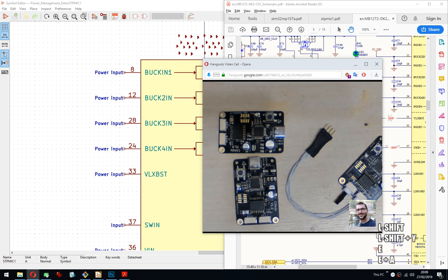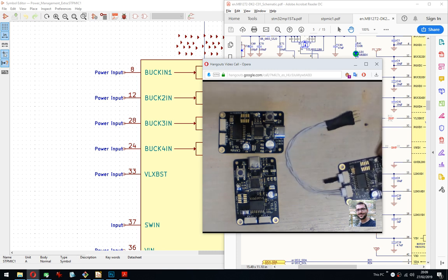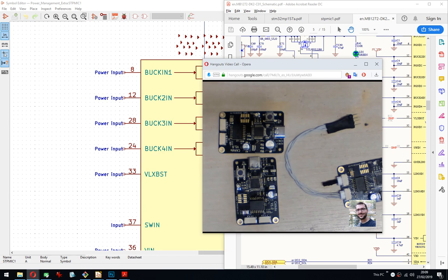Yeah, there's a hot glue gun and the oscilloscope and lots of tape and components and FPGAs and whatever. But yeah, I plan on doing some rudimentary TX testing and looking at the frames, if I'm even capable of sending anything, because I've figured out that the issue I was having, that I can't pull up the CAN device on Linux, was because the CAN transceiver wasn't powered on the other side of the isolation.